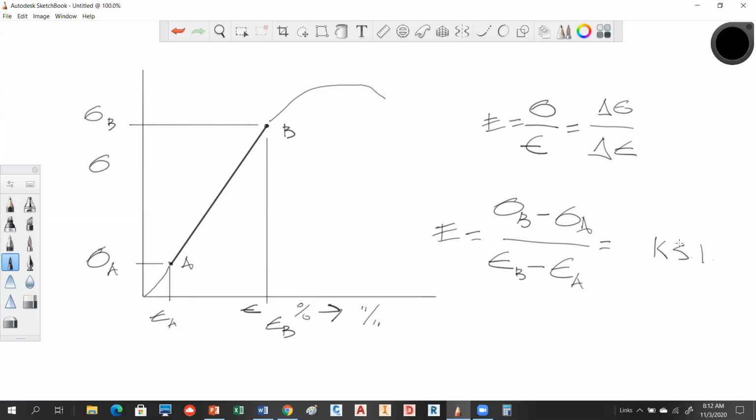Yep. So that's step 2. You've got to determine your modulus of elasticity. There's a steel sample and there's an aluminum sample. After you do that, it asks you to compare those numbers to the published values, okay? And they give you those for steel and aluminum. Then they want you to decide whether you're close or not, okay?